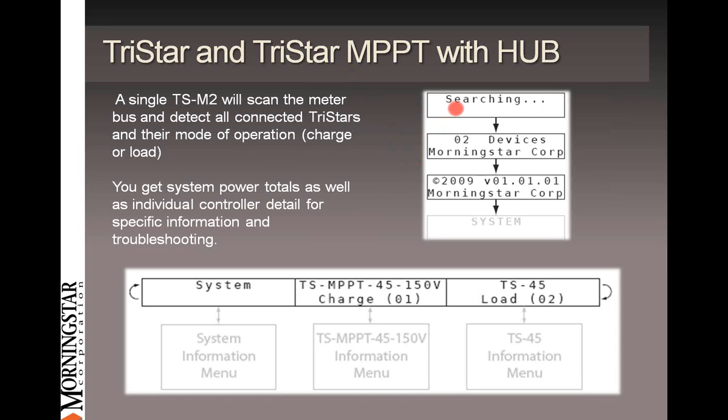In this case, each TriStar operates just fine independently with its own RTS and does not have to share that information. Since the RTS is included at no cost, it just gives you some good redundancy. But if you were to lose any one of those controllers, the rest will remain in charge just fine, with only a little bit of loss of the array.